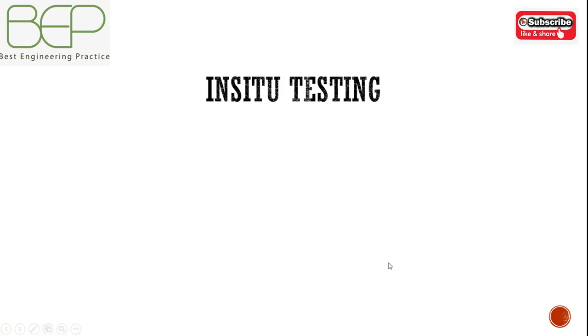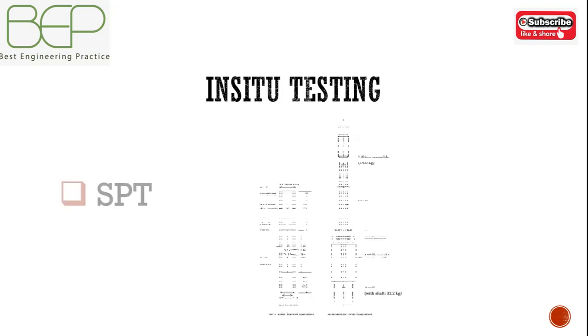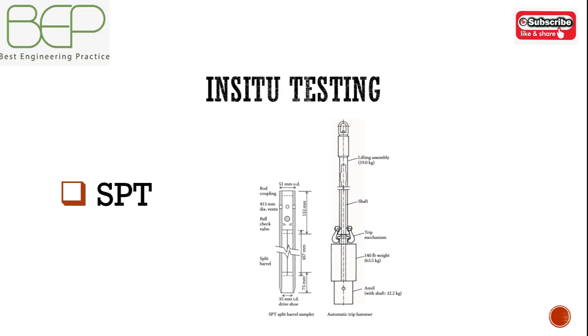The two main types of in situ tests used around the world are the standard penetration test (SPT) and the cone penetration test (CPT). The SPT test is carried out in a borehole and essentially involves counting the number of hammer blows that are necessary to drive the thick wall tube 300 mm into the ground at the bottom of the hole. Points to note are: